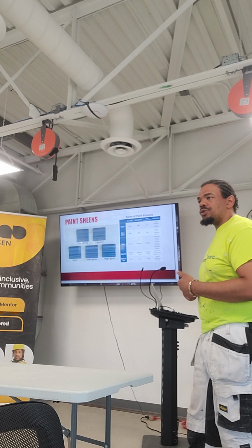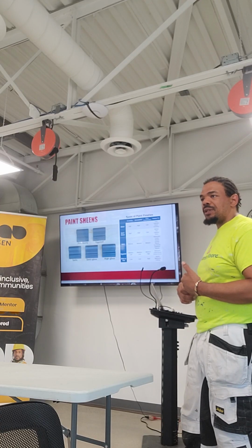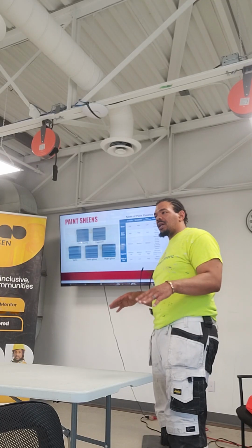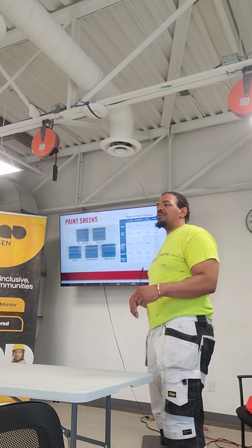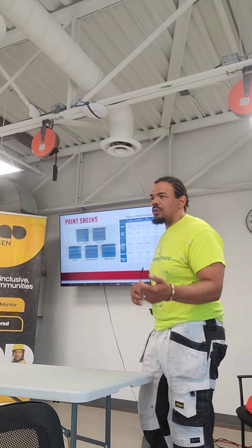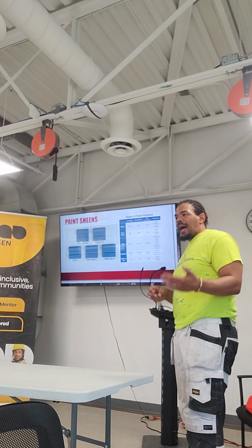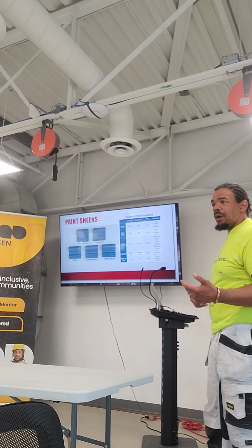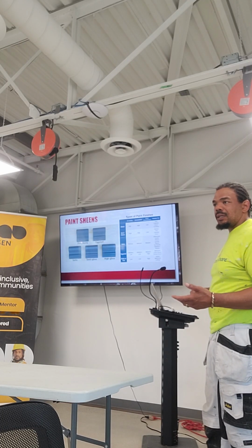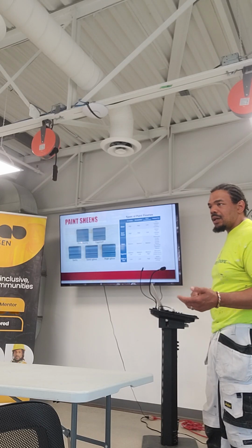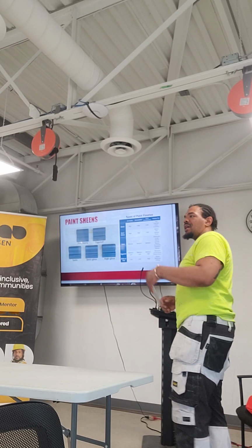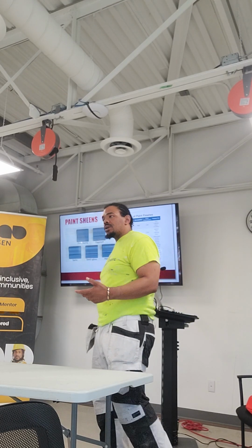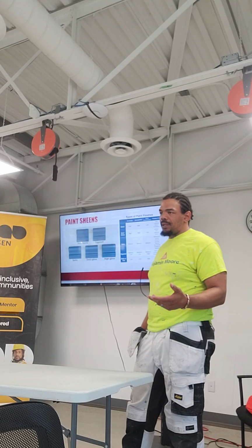But a high gloss, usually they reserve that for solvent-based finishes, because solvents will lay down a lot flatter and they'll look a lot glassier and glossier. So they're more designed to have the performance that a high gloss coating would need. Matte paints you'll see are primarily oil and latex, or oil and acrylic and latex. So you can have a matte paint for anything. We're going to use our demo, and the paint that we're going to use for our demo is going to be a latex matte.